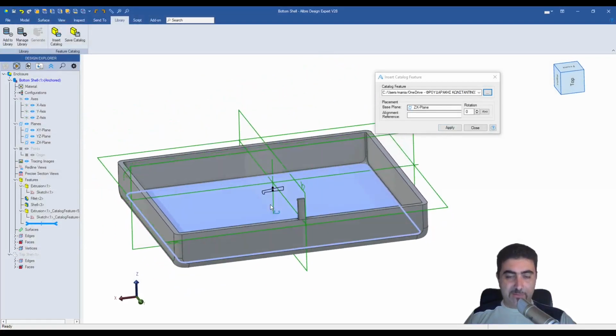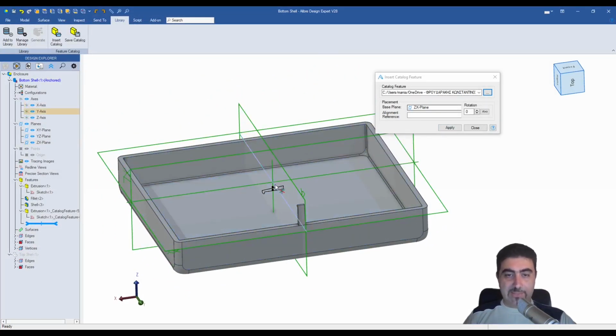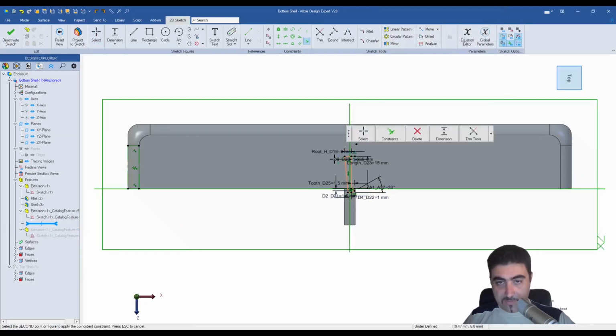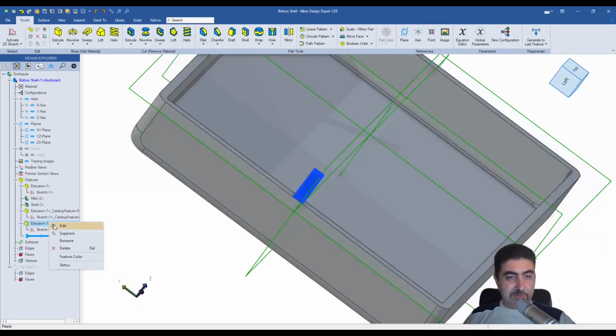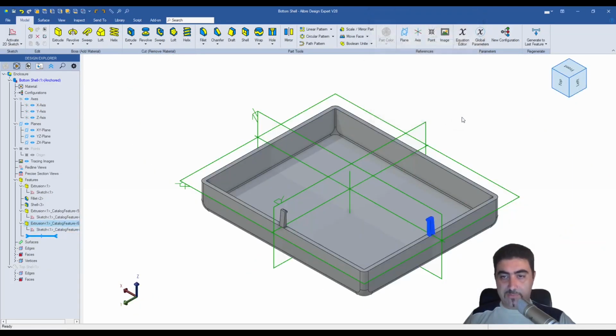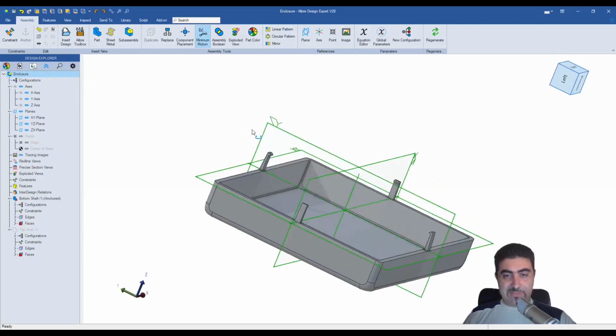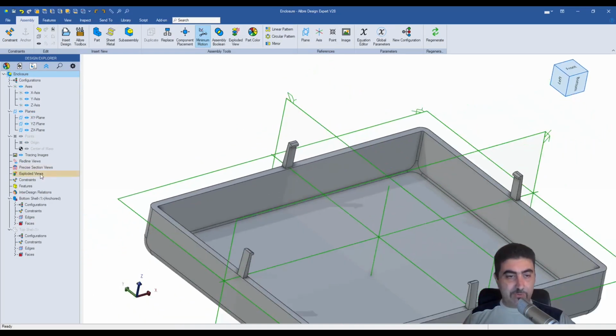Okay, so it came out with the completely wrong orientation. In that case, what I'll do is I'll hit alignment reference and give it an edge here. That brings it upside down. Let's see if I select another edge, will it fix that? No, well, I can fix that with a rotation of 180 degrees. So that's okay. I go in here and I tell it, look, snap this point, this point. I will do the same thing. We'll just make this into a mid-plane as well. Now we'll mirror things around. One there, and we got one there. We've got our snap hooks on the bottom enclosure, right?